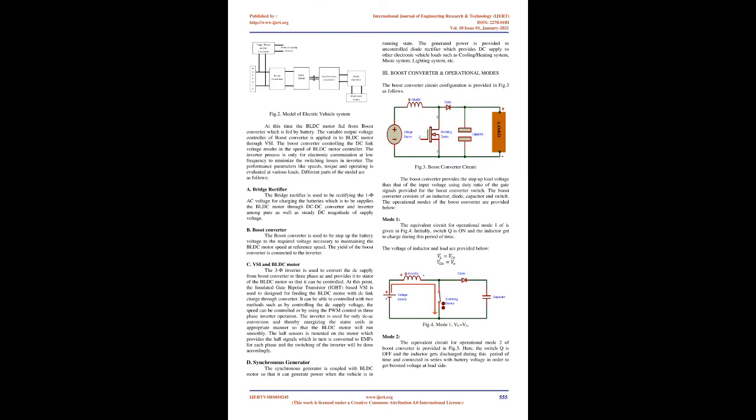The international standards of power quality such as IEC 61000-3-2 reject such power quality issues in three-phase source. The switching losses and power quality issues at the supply side are reduced by the planned control strategy in BLDC motor with varying DC link voltage fed to voltage source inverter. This results in the inverter operating with only electronic commutation, which is much required for BLDC motor operation at low frequency. Brushless DC motor with DC-DC converters such as Luo, modified Zeta converter, etc.